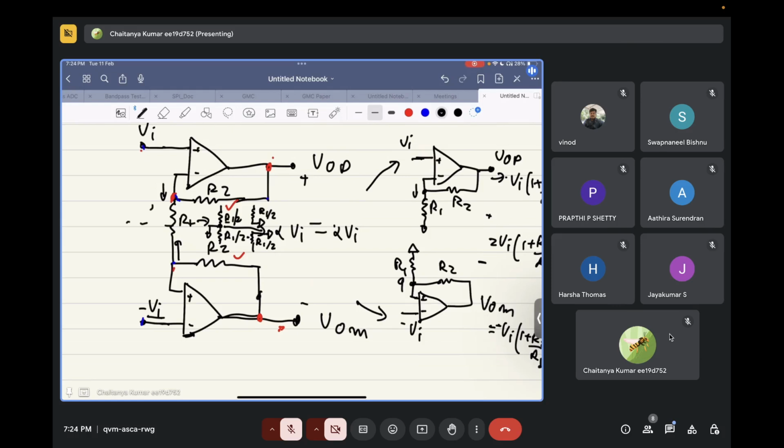If there is some resistor that is cutting the axis of symmetry, you split it into half resistors, for inductors half the inductance, and for capacitances double the capacitances, and put a ground between them and analyze both the halves of the circuit separately, and their overall addition will be the output voltage. And for the common mode, whatever is there on the axis of symmetry will just get shorted.